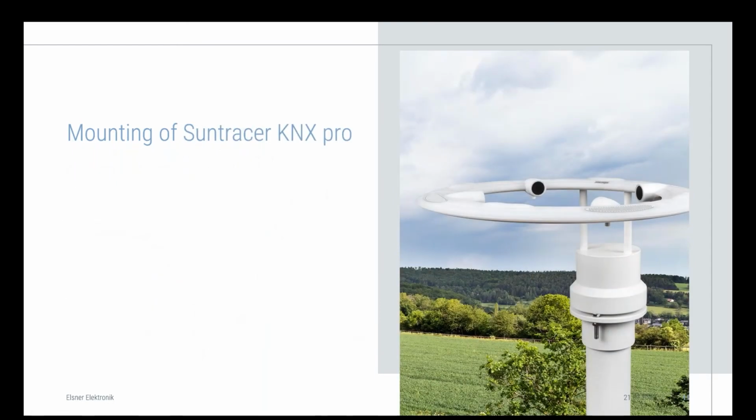Next up, we will discuss the mounting of the Suntracer KNX Pro. The Suntracer KNX Pro weather station must be mounted on a mast on the building due to the wind direction measurement. So here you can see the Suntracer on a mast. The mast extension as well as suitable mounting material is included in the scope of delivery, so you do not need to purchase this extra.